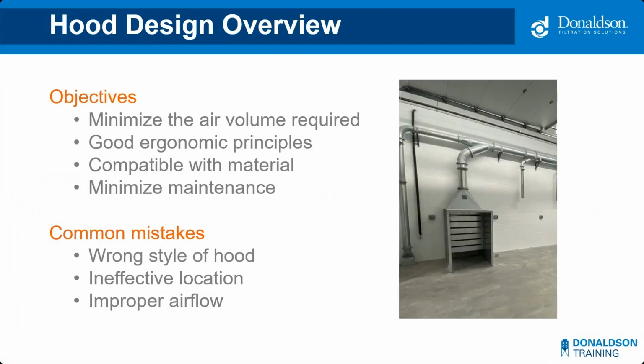It should be designed with good ergonomic principles. It should be compatible with the material flowing through the work area, and it should be designed to minimize the maintenance and other activities that may disrupt your process. When it comes to assessing an existing system, some common mistakes that we see is the wrong style of hood being used, the hood's not located in an effective position, or you have inadequate airflow at the hood.